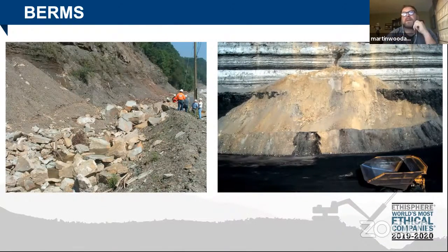Berms are very, very effective. They have a high capacity for absorbing energy. But sometimes the only problem is, if it's just a pile of material, it needs a wide base to be able to catch the rock. So it's not very efficient, especially next to a road. It's used in quarries and mines a lot because you have a ready amount of material that you can move and put into place. That's why you see this as a delineation in many mines and quarries.